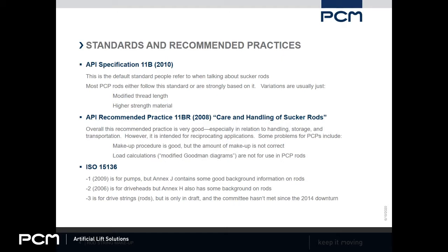Also, the load calculations that are in that recommended practice, they're called modified Goodman diagrams. Those are specifically for the reciprocating application. There's no mention of torque strength in there at all. But overall, it's still a good document, especially for looking at handling, storage, transportation.